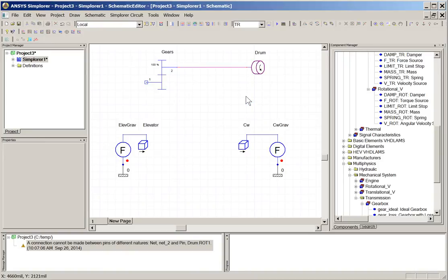So that's done. It's going to be a coordinate transformation. The drum has a cable draped over the top, and one side hangs down on the elevator side, the other on the counterweight side. So if you remember the basic geometry, the ratio of the rotational speed to the linear speed at the tangent point on a drum is equal to 1 over the drum radius.